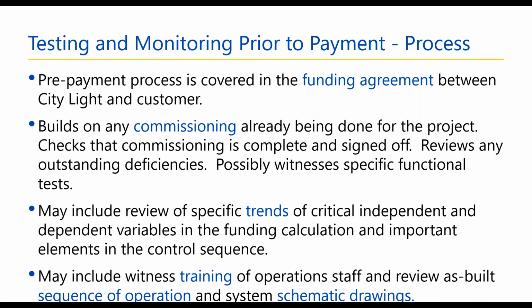Increasingly, with the types of things that we're monitoring and testing, understanding the system is not easy. So before moving to reviewing trend logs, make sure that you've written down, you've looked at the sequence of operation, and you check that whatever trends you're looking at and your own understanding of the system are directed by the designer's sequence of ops, as corrected if necessary by the contractor.